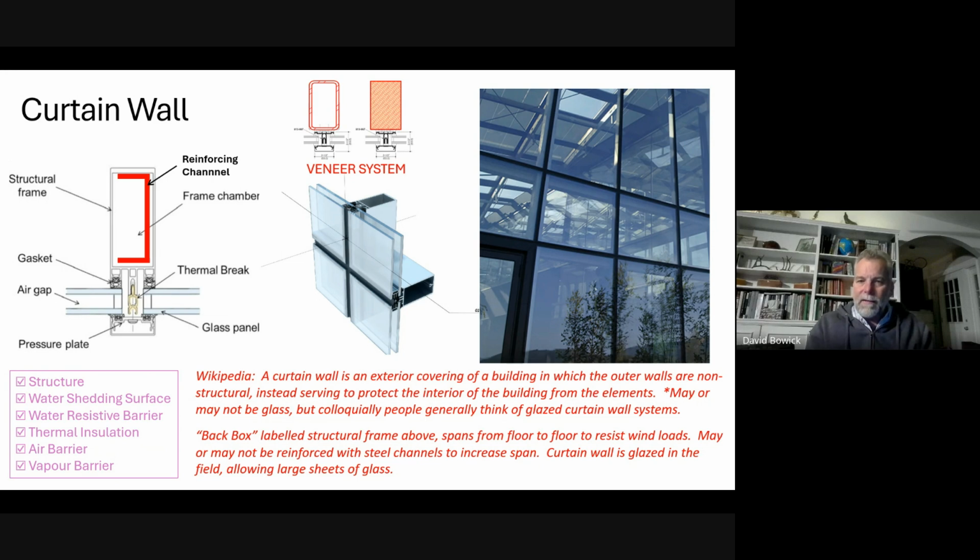So we can imagine that we can screw it to structural steel. This allows us to take advantage of the extra strength and stiffness of structural steel as our mullion, as opposed to aluminum. Steel is 3 times stiffer than aluminum. So the members can be smaller if they're steel.